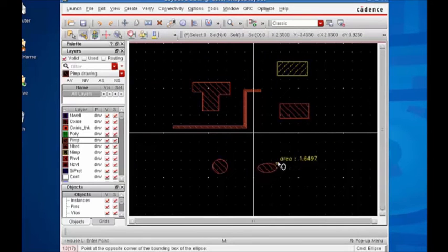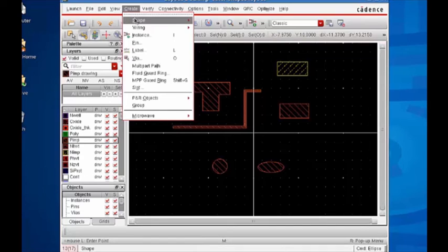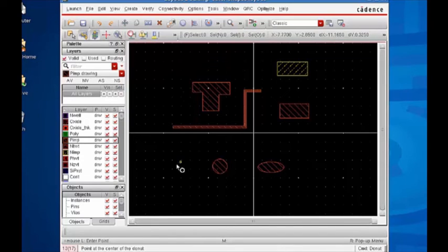So I got the bounding box, and then based on where I go with that bounding box, that's going to be the shape of the area of the ellipse. Okay. So if we say create shape donut, point at the center, now point at the inner edge, point at the outer edge. Okay. So there we've made those shapes.